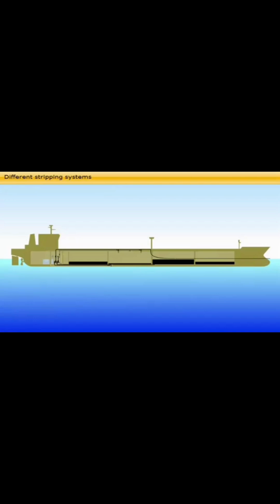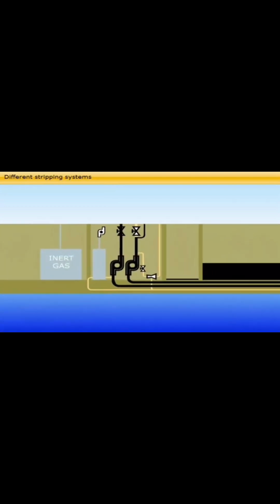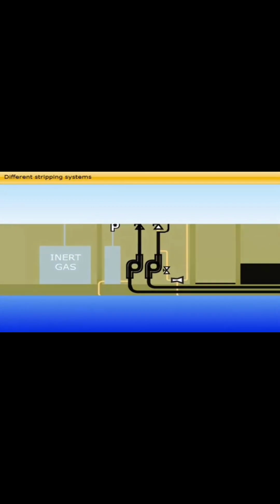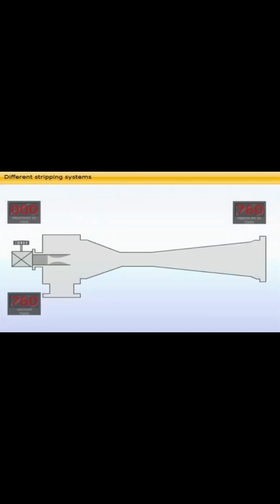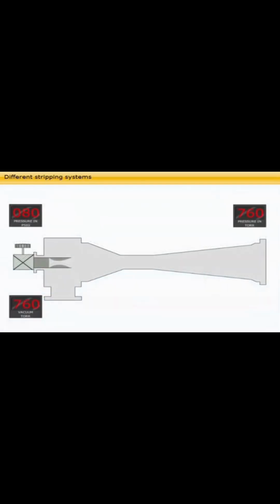In the final stage of the crude oil washing, bottom crude oil washing for removal of sludge and sediments, the stripping eductor is used, as well as for final draining of all cargo tank bottoms and lines. The stripping eductor is driven by either a cargo pump or a separate crude oil washing pump. The driving fluid and the drainage from the tanks are delivered into the primary slop tank. The slop tank will then be the last tank to discharge with one cargo pump.